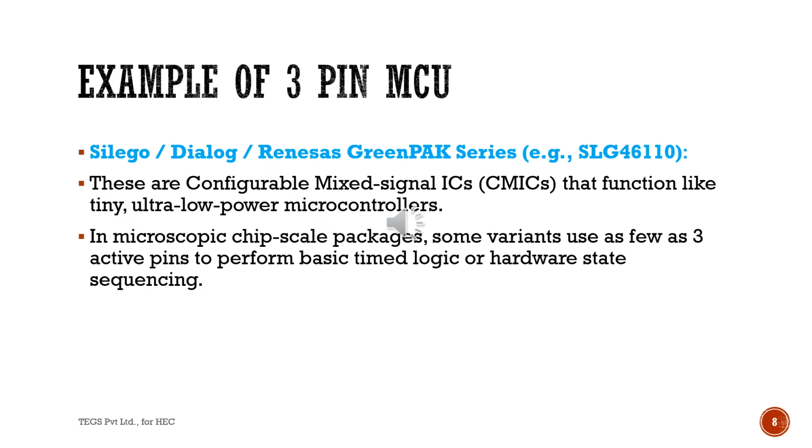Example of 3-pin microcontroller unit: Silego, Dialog, Renesas, GreenPAK series. Example SLG46110. These are configurable mixed signal ICs that function like a tiny ultra low power microcontroller. In a microscopic scale package, some variants use as few as 3 active pins to perform basic timed logic or hardware state sequencing.